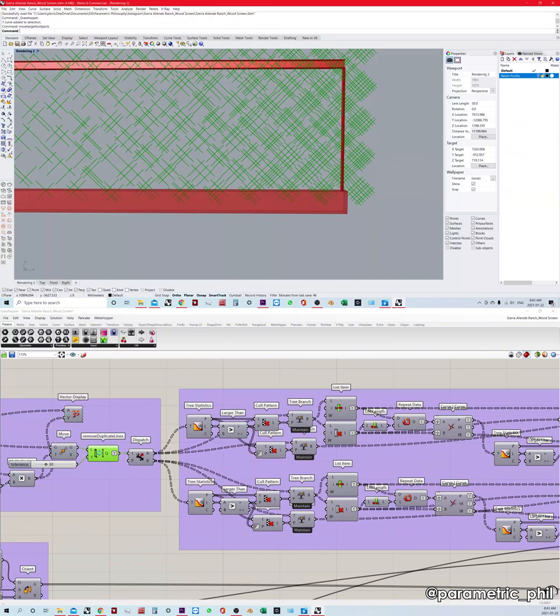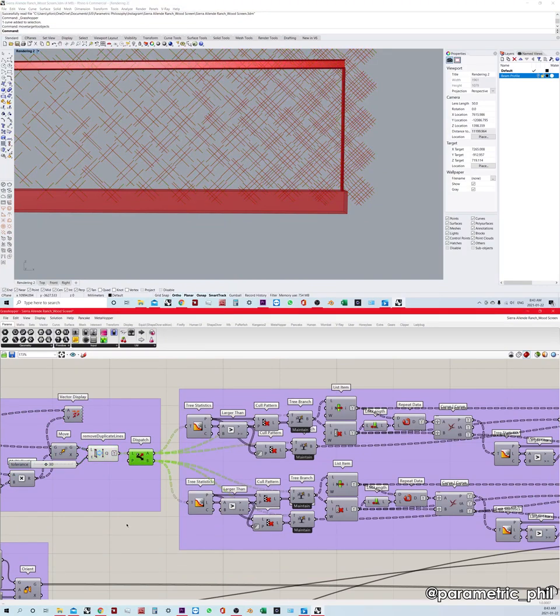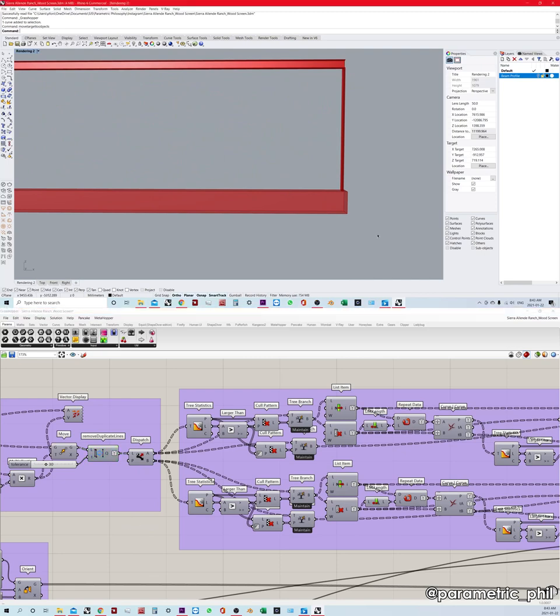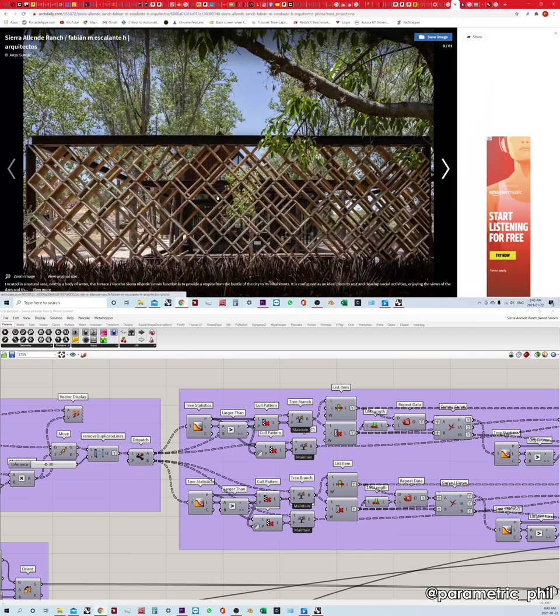Now, we use a dispatch component to split this list up into A and B. We're using a true-false pattern, so it's an equal length list in A and B. Well, roughly equal. And the reason we're doing that is because if you look closely, you can see there's actually 2 depths. So our main grid is like a 2 by 12, it looks like, maybe a 2 by 10. But you can see the partial pieces, the pieces inside. Look at this one. It's in front, and this one's in the back. So we actually have 2 depths.